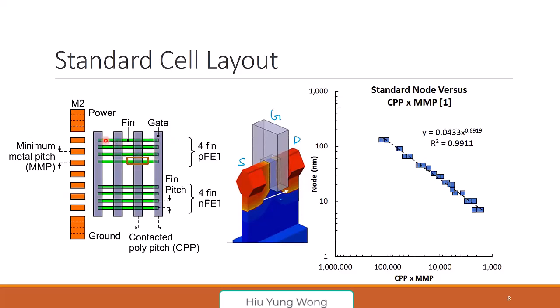So for example, this may be talking about two transistors in series. Then, for example, this will be source. This is the drain of this transistor, and then this is the source that is connected together with the drain of this transistor, and then this is the drain. So it doesn't matter which one is which. It really depends how you connect it, how you bias it. Because if you look at this 3D structure, the source and drain are equivalent. You cannot see the difference. The only difference is when you apply the bias. This is the same for the planar, right? Do I answer your question?